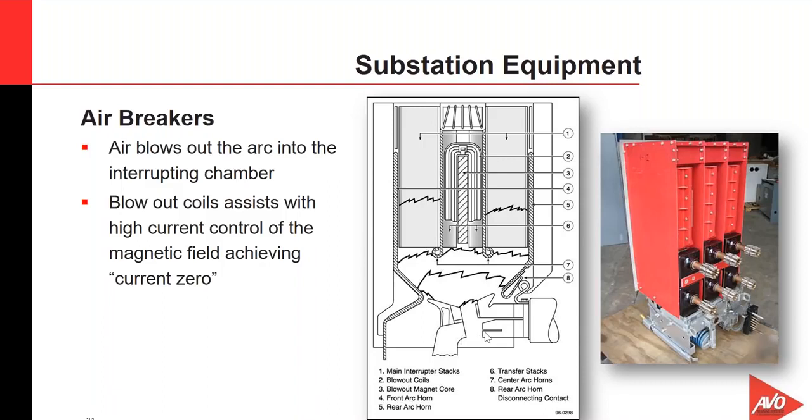Okay, and another one that I feel is of a simple operation is a vacuum type of circuit breaker. With this vacuum type of circuit breaker, we've got a set of butt contacts internally, and these butt contacts are obviously going to open and close via this movable shaft. Okay, we've got a metal vapor condensing shield that surrounds the electrical contacts on the inside, and then we've got this insulating envelope on the outside that's usually made out of glass and porcelain.